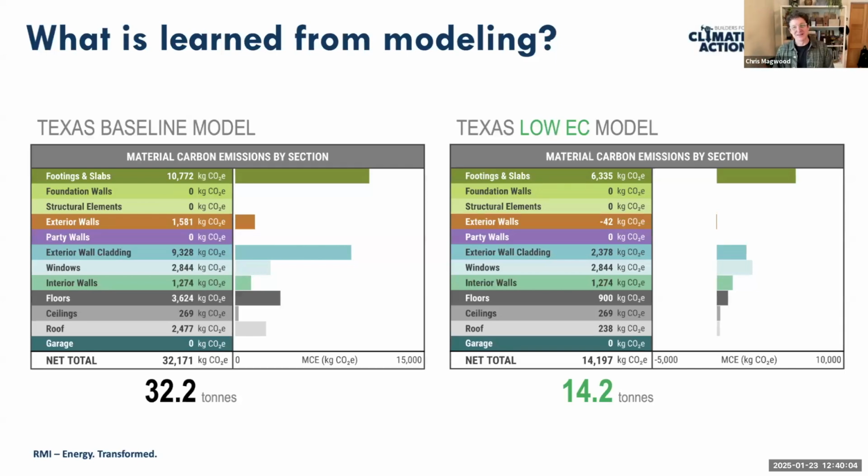If you've seen that cellulose insulation is the lowest embodied carbon insulation that's practical for you, you don't have to run the model every time. It's going to tell you the same thing every time. So if you can talk to your concrete supplier about a 40% slag or 40% fly ash concrete or something like that, it's always going to be 30% less, and you don't have to model it every time. But it is helpful to make the model to sort of see where those things are.